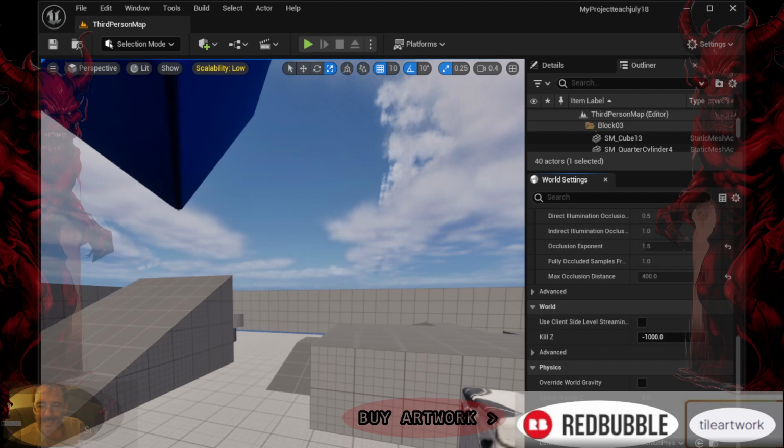2. Create a new project. Once Unreal Engine is open, you'll see the Unreal Project Browser window. Click on the New Project tab on the left side of the window. 3. Select a template. Unreal Engine offers several project templates to choose from, such as games, architectural visualization, film, television, and more. Select the template that best fits your project type.